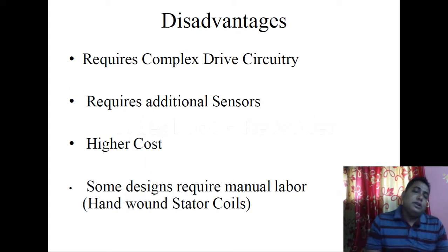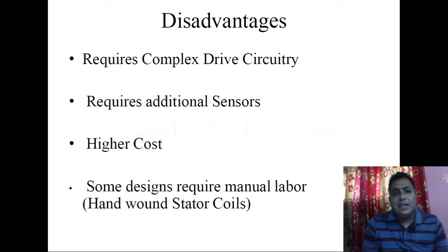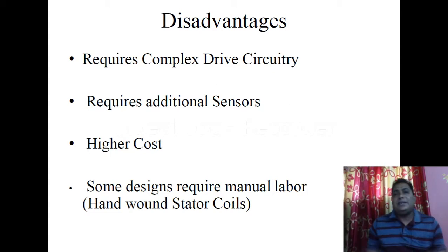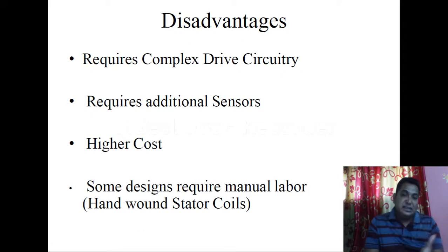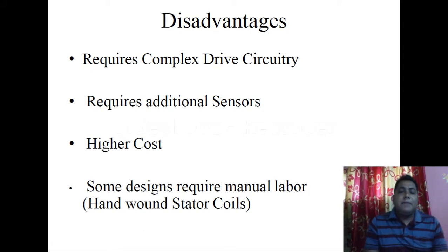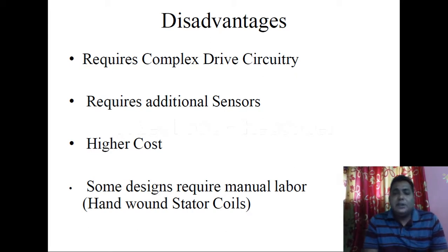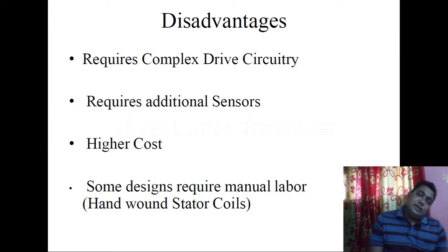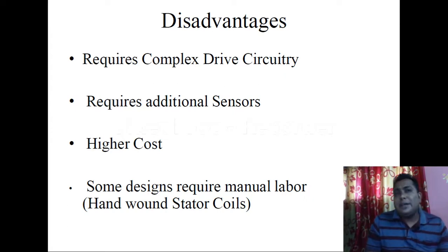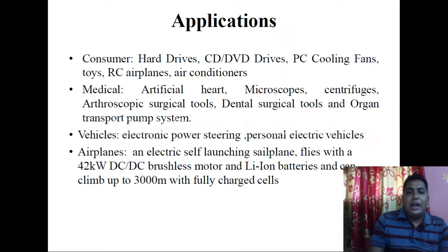Now coming to the disadvantages: it requires complex, yes obviously we need some electronic devices, some sensors to run this BLDC. So it requires complex drive circuitry, requires additional sensors, higher cost, some designs require manual labor, but in other respects it has more advantages.